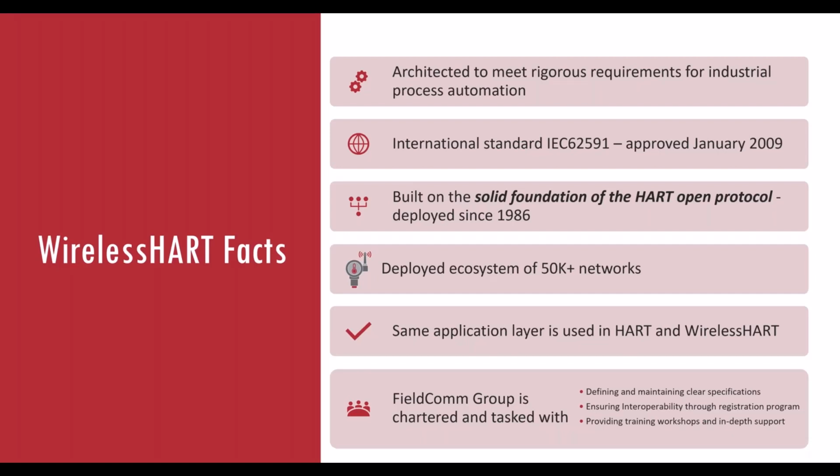and it is built on the solid foundation of the HART protocol, which, as probably most of you know, has been around since the 80s. At this point, there are about 50,000 plus WirelessHART networks deployed worldwide, and this is one important fact. WirelessHART uses the same application layer as wired HART. Now we will talk a bit more about that in some of the other slides that will follow, but that's something that I would like you to keep in the back of your mind.